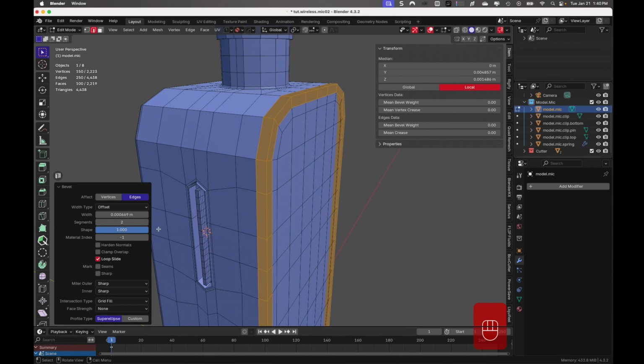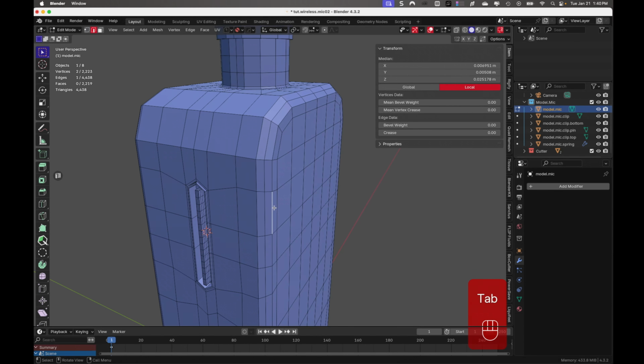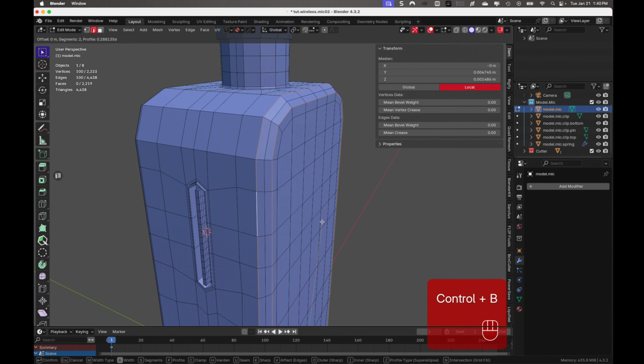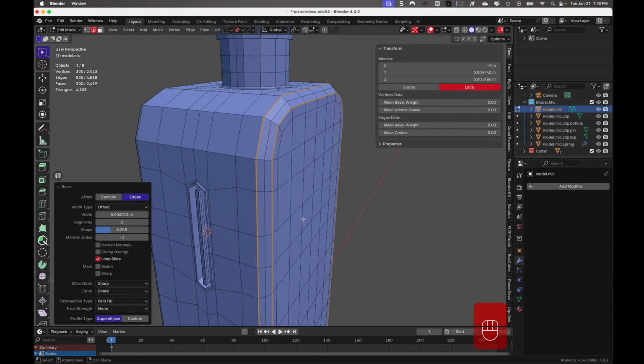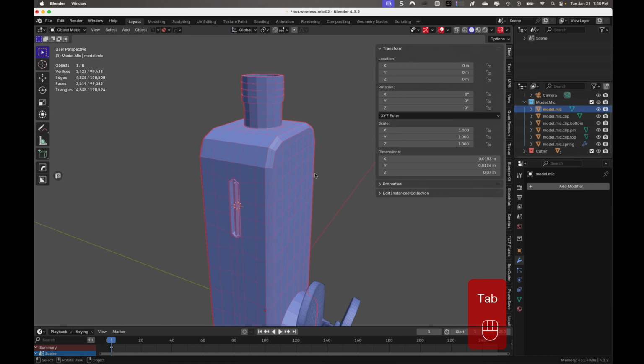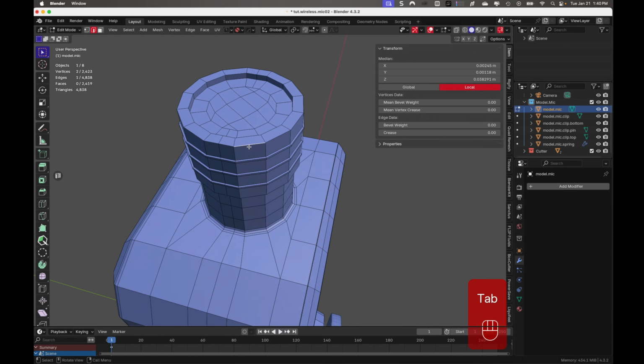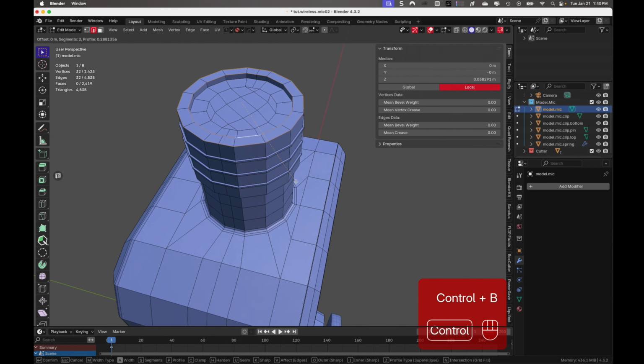I'm going here to change the profile to this bevel because it's almost like a chamfer. But I don't want to add a level of one and create an extra chamfer. I actually want an extra loop cut in there. And then now I want to bevel those two edges to make sure that they're pretty sharp. Okay. And I'm just looking at everything where I don't have bevels, and I'm making sure I have the appropriate bevels there. If that makes sense.